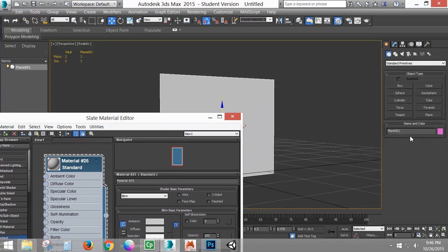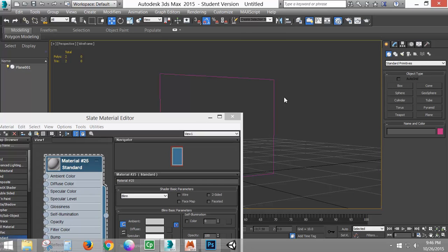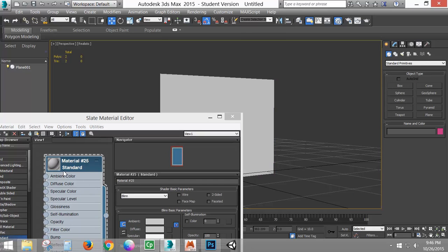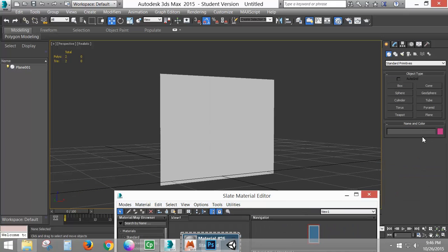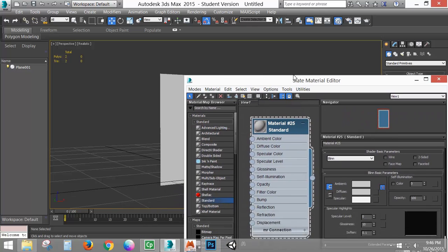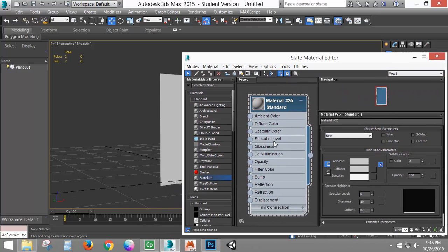And you can see my object color here, which was pink, and if I go into wireframe right now, we can still see that pink is being overridden by the material color. So just to give you an idea of how materials work, this object color is merely for objects and organization, whereas this is an actual material that we'll see. Nice part about that is I can easily tell it to be two-sided or not, or I could turn that off, which is nice to have.